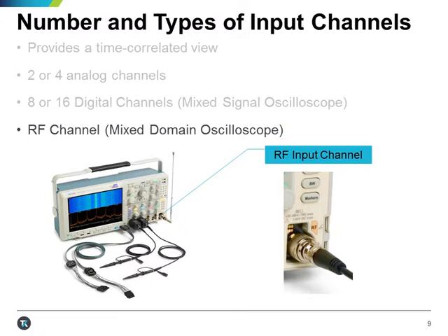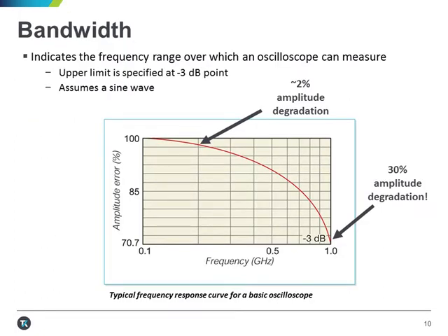Having a spectrum analyzer within an oscilloscope fulfills this need and also saves a ton of bench space due to integrated instrumentation. Bandwidth is one of the key specifications that determine how a scope relates to the signals you want to look at. Scope specs usually represent the bandwidth in two ways, either as the -3 dB frequency at the high end of the bandwidth or as a scope rise time. The two specifications are related. First, we'll talk about the usual way of specifying bandwidth. All oscilloscopes have a low-pass frequency response that rolls off at higher frequencies.